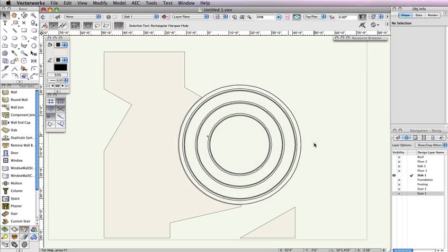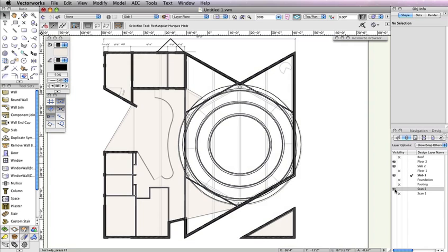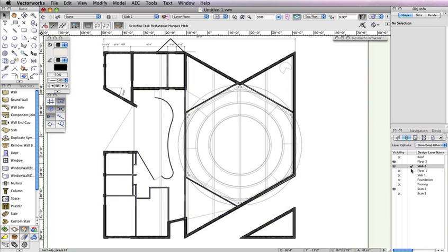The first floor slab is done, so we'll be continuing on with creating the second floor slab. In the navigation palette, set design layers Slab 2, Floor 2, and Scan 2 to be the only visible layers. Also, make Slab 2 the active layer. Just as with the first floor, much of the slab creation will rely on the existing walls, but this time the walls we use as a reference will be from Floor 2.